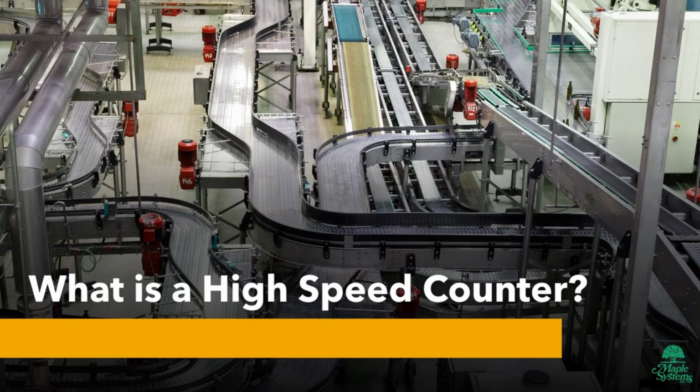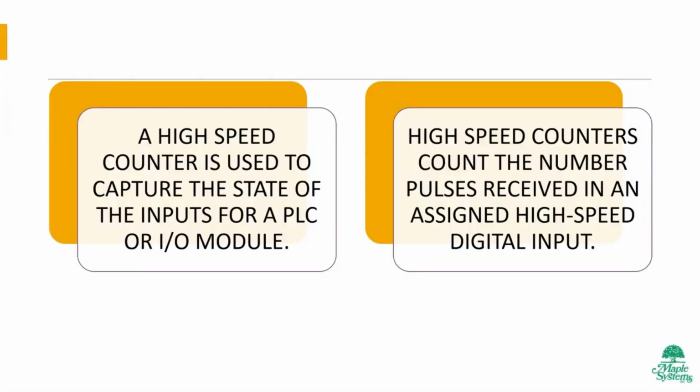High-speed counters are used in industrial automation and control systems to count events or pulses at a faster rate than normal counters. High-speed counters are designed to handle high-frequency input signals and are used in applications where precise counting and timing are essential. A high-speed counter is used to capture the state of the inputs for a PLC or I/O module, and they are used to count the number of pulses received on an assigned high-speed digital input.